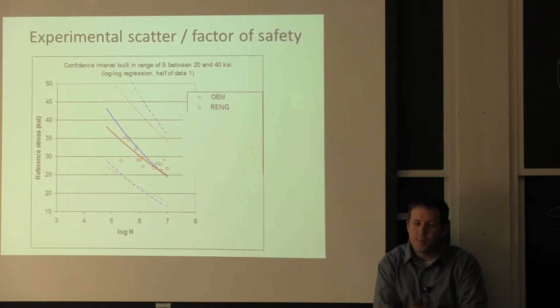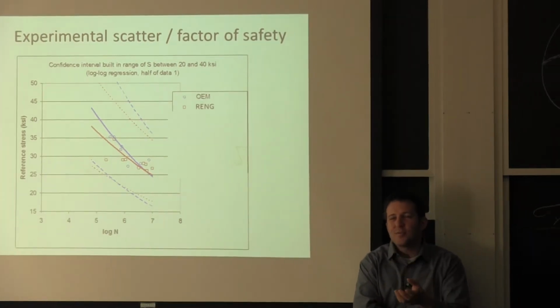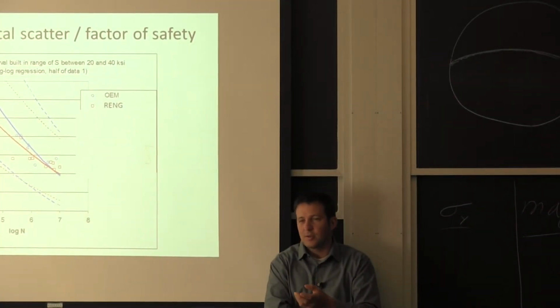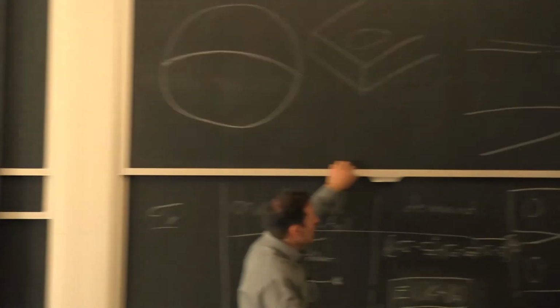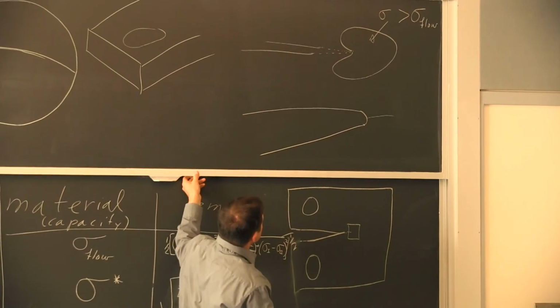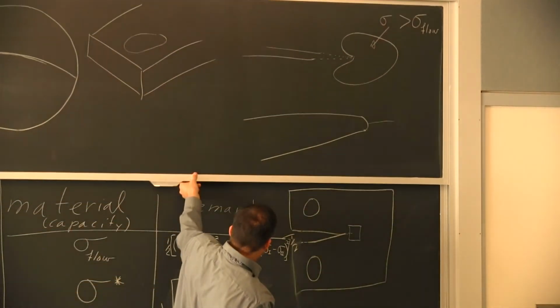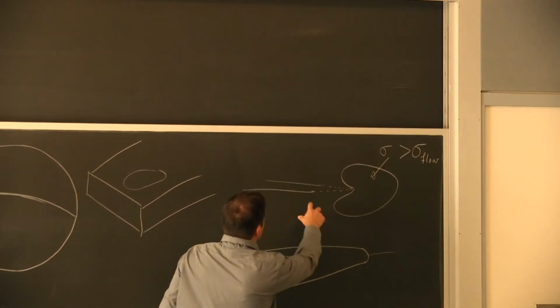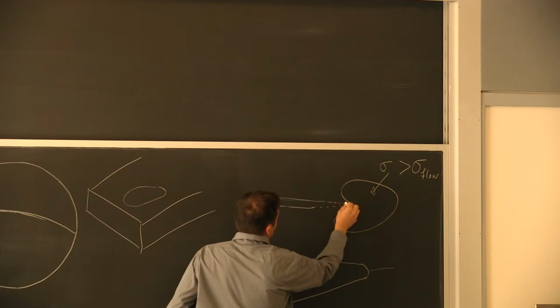The aircraft, what happened is, depending on the alloy you use, you have a lot of variation in that stress corrosion cracking resistance, because the alloys affect the stability of the little oxide that we were talking about. Where did we talk about that one? Yeah, I think it was right here. So I just mentioned that you were going to have that little protective film.